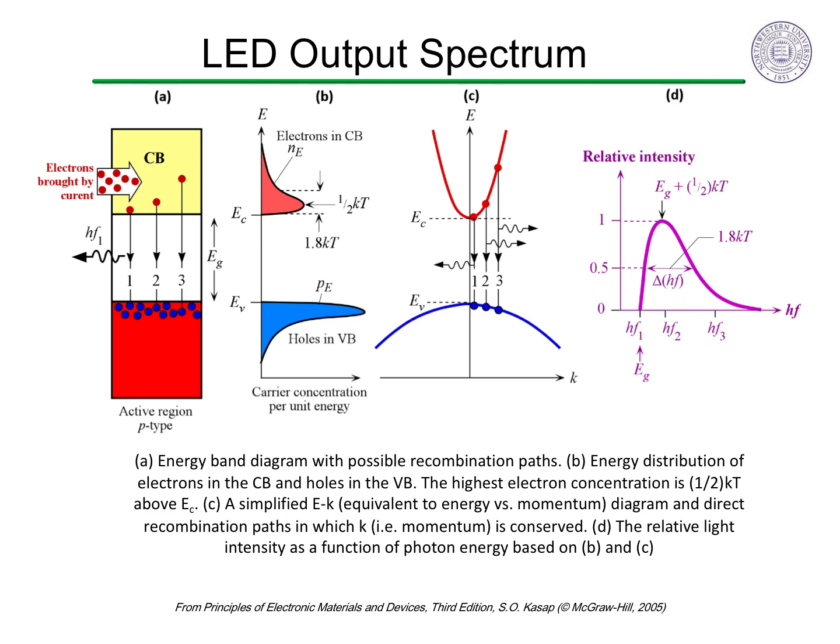band edge. Because the efficient direct transitions are vertical in the E versus k diagram, the lighter band is going to run out of electron or hole states sooner. The emission spectrum should look like what we call the joint density of states, considering all the possible transitions of possible electrons to holes, which is a convolution of the valence band density of states, the conduction band density of states, and the distribution function.